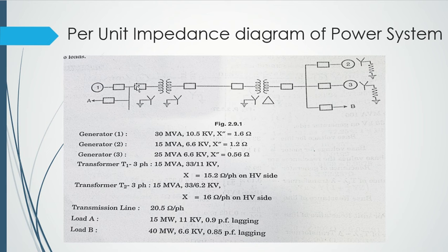And then we have 2 circuit breakers. After the first generator we have a circuit breaker, then the line for the load is drawn out, and then we have a second circuit breaker. Then we have the first transformer. This is a transformer with two star windings. Both of the windings are ground connected.